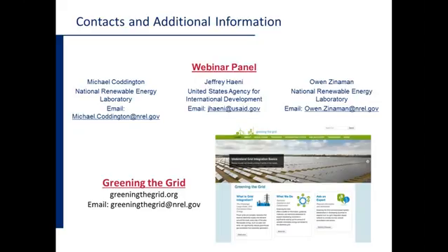And over the years, inverters in Germany were programmed to all drop off if the frequency got above 50.2 hertz. And that became a major problem, and one that they've had to go back and spend hundreds of millions of euros trying to reprogram and solve. Because if you're generating more power than you consume, your grid frequency will start to rise. And when that happens, again, all of these inverters were programmed to drop off at 50.2 hertz.